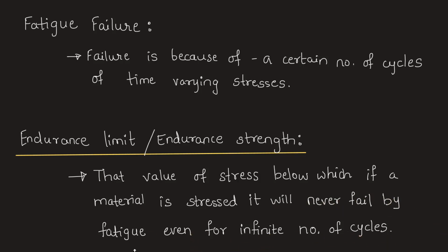If a load causes the material to be stressed under the endurance limit with reversal nature, it will never fail. But if there is a stress above the endurance limit over a certain number of cycles, the material may fail due to fatigue. There are chances of fatigue failure if the stress is above the endurance limit and cyclic in nature, of course. But if it is below the endurance limit, there are no chances of fatigue failure, even for millions of cycles of reversed stresses.